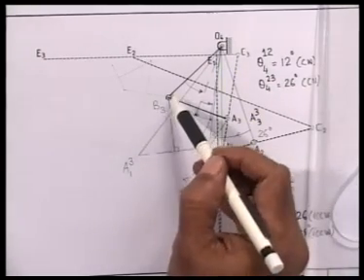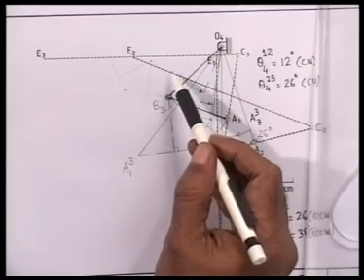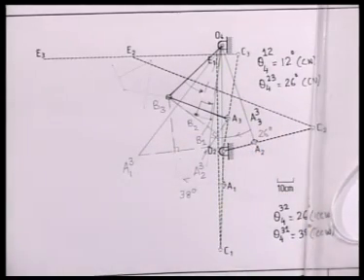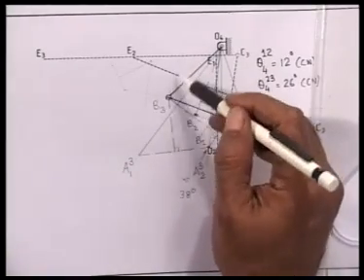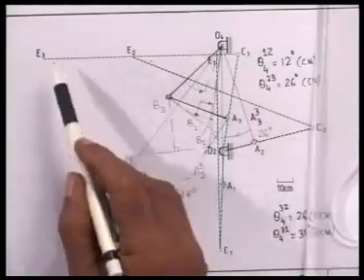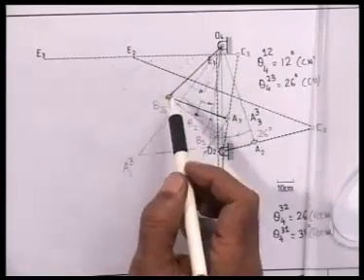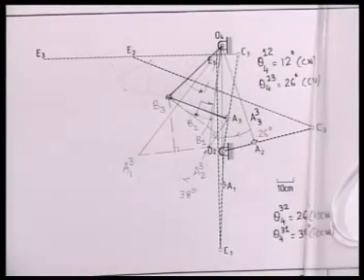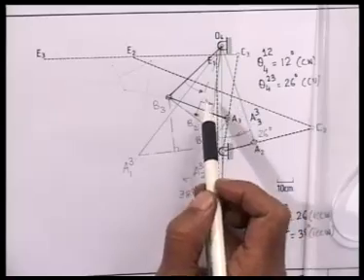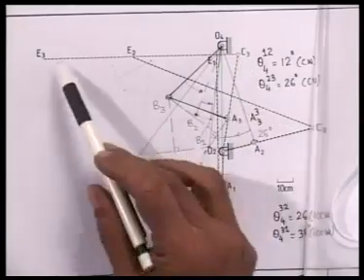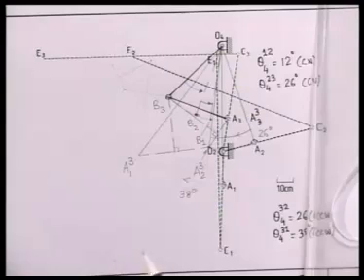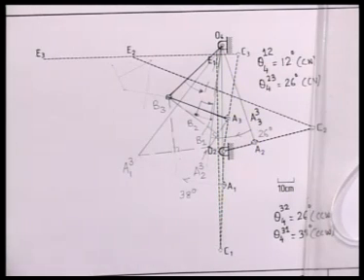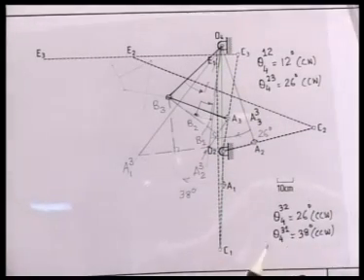To locate the hinge on the door board D, I have to hold the door board fixed, because BD length is a constant length. So if we hold link 6, that is the door board, fixed, then B goes on a circle with D as center. So we make a kinematic inversion holding the door board always fixed at its third position. To obtain the inverted positions of B2 and B1, we use our procedure of kinematic inversion and use a tracing paper.